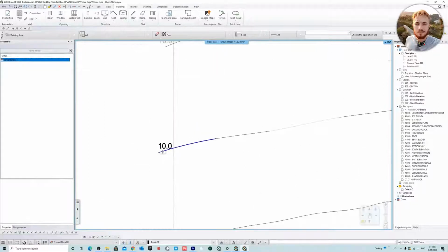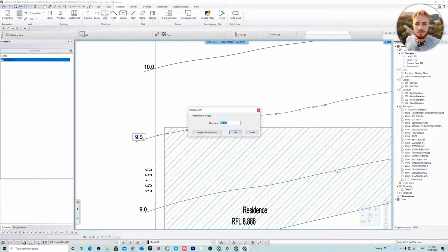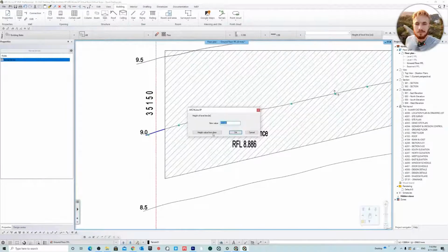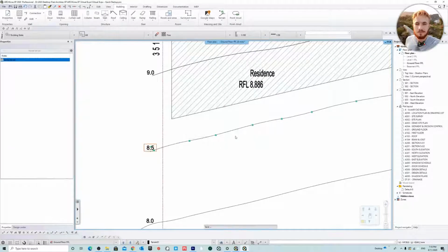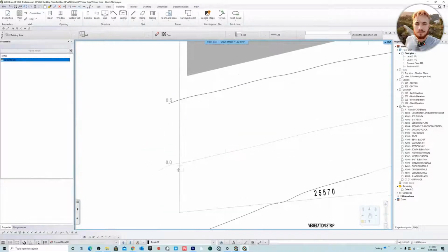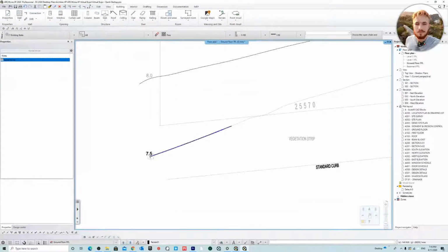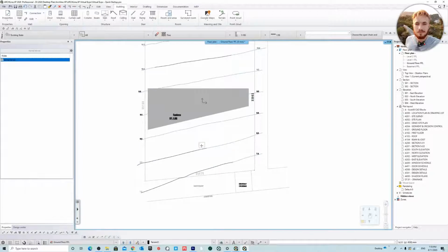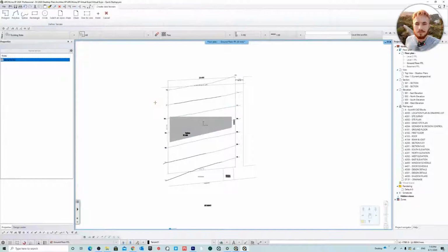So we're going to go ahead to our second line and select it. Hide from draw and just select the dimension. Do this one as well: hide from draw, select the height. We're going to keep doing the same for each line: hide from draw, select the height. And quite easily we are able to select everything quite quickly, and we'll just go to enter and enter again.